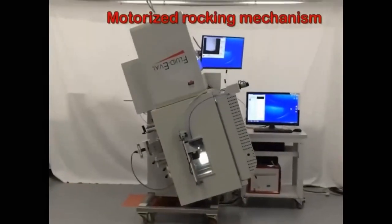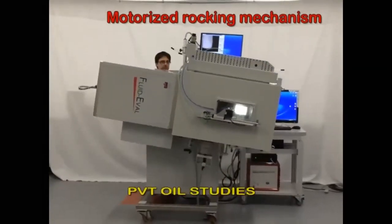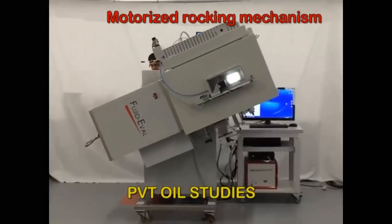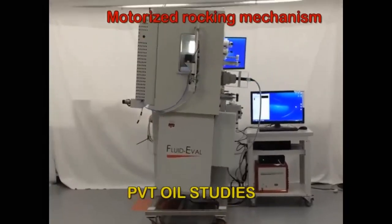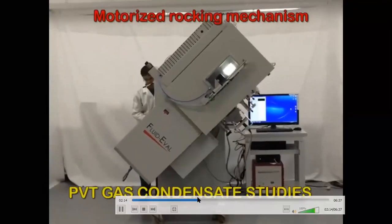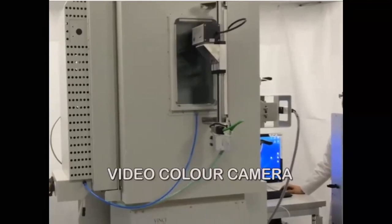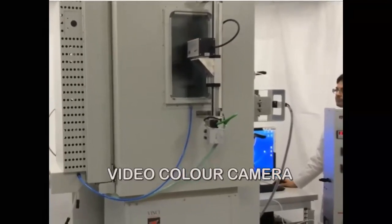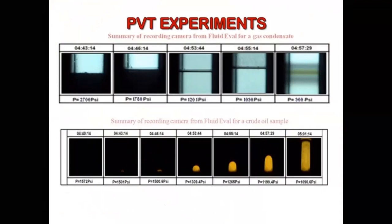A motorized rocking mechanism enables the end user to set the PVT cell in two possible positions. For PVT oil studies, the cell is in an upright position and the gas is released by the operator using a dedicated bleed valve. For PVT gas condensate studies, the cell is inverted. A uniform lighting box and a motorized linear stage capture high-resolution pictures of the sample being analyzed under specified pressure and temperature conditions. PVT experiments are recorded in real time and the results can be retrieved after the test for post-treatment.